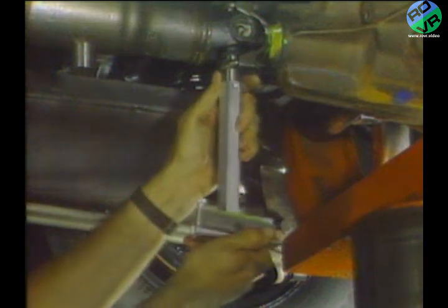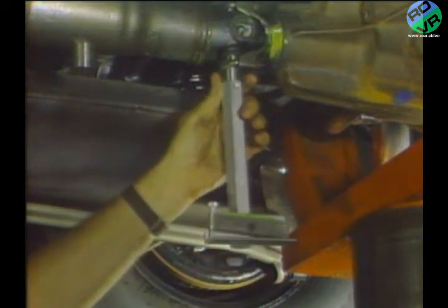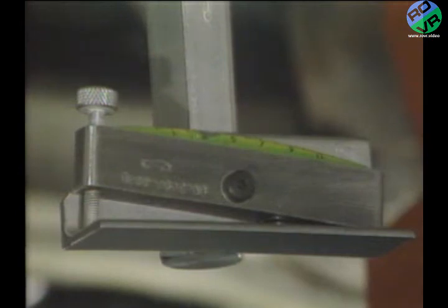And finally, driveline vibrations can sometimes require a pinion angle check with use of a special magnetized bubble gauge as you see it here. The complete procedures for making the various driveline diagnostic checks are fully described in your Vehicle Vibration Diagnosis Guide. Refer to this helpful booklet often when diagnosing driveline problems.